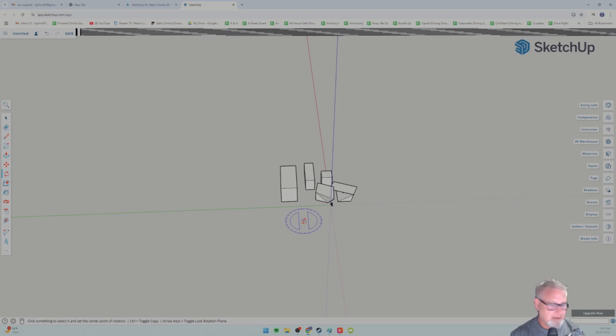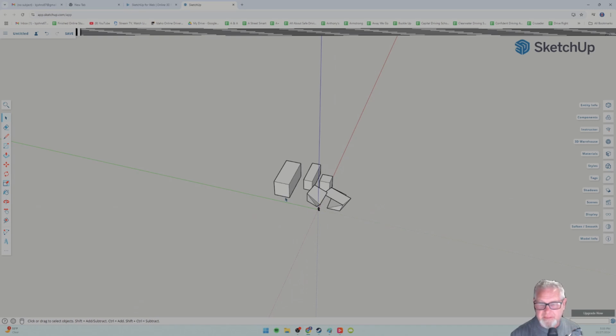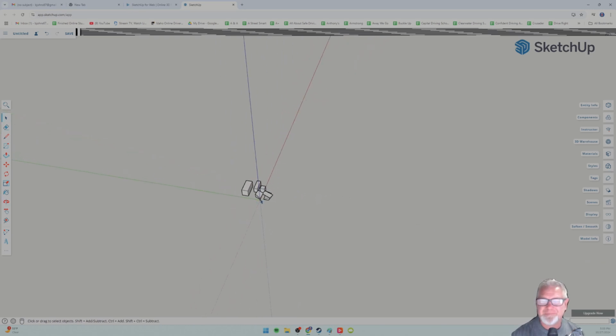Let's get off of that tool. The left mouse button is just for selecting. Right mouse button will let you right click on things, and there are some other options that'll pop up, and we'll get to those. And so the other thing that's important is you hold down the shift key, and let me just think here. Shift key, or is it control? Oh, that's what it was. Okay, so it's mouse wheel, push down the mouse wheel, and the shift key. That's called panning. So it doesn't actually move your shapes, it moves the screen.